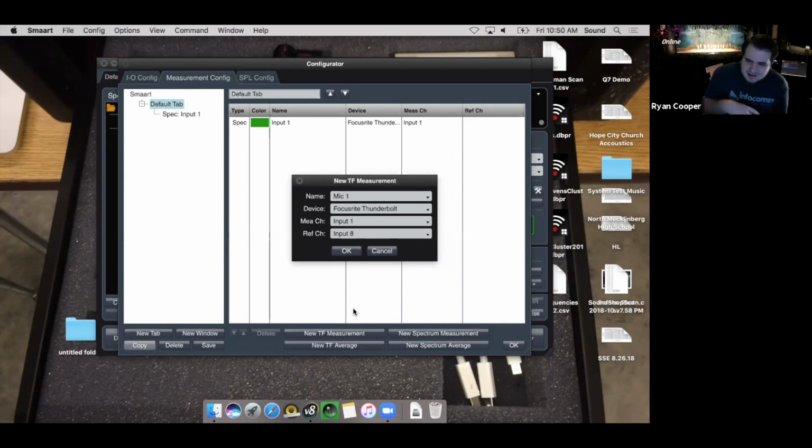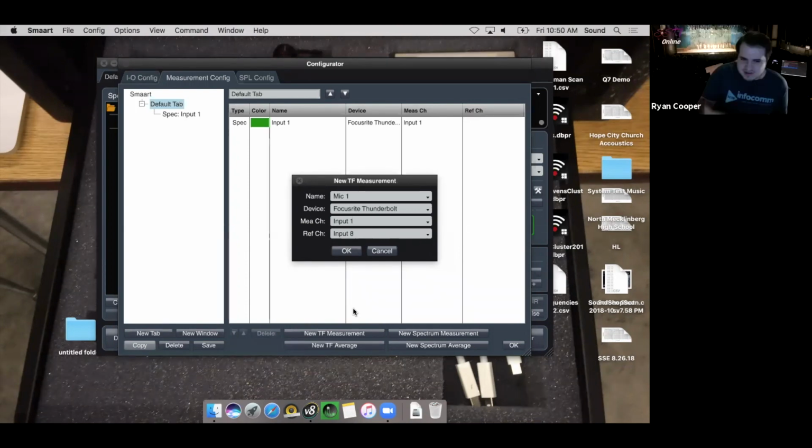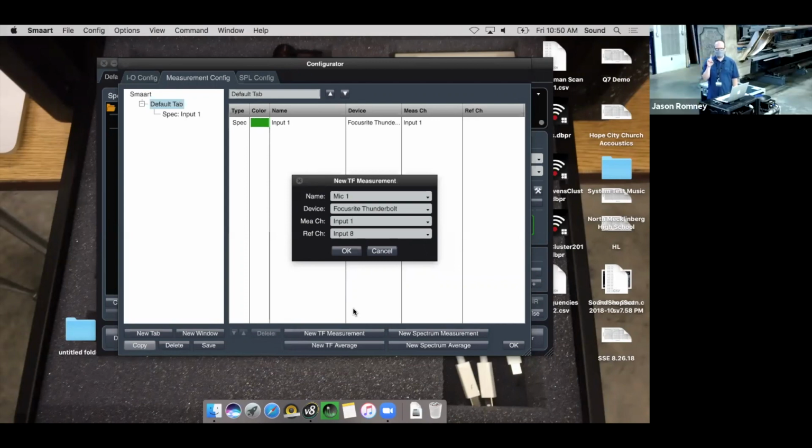Just doing the analog loopback also means that any acoustical or electronic properties of the interface, like any magnitude changes in frequency response or delay changes. Oh, those would both be reflected. Yeah. And none of those affect your measurement. Yeah, so theoretically there should be nothing that happens to this sound as it's going through this little wire that's looping back into the computer.